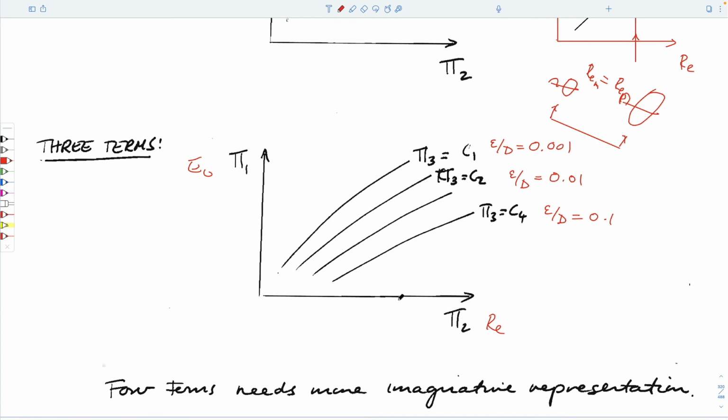But again, if we get, what do we call it, kinematic similitude, that the Reynolds numbers are the same. Reynolds number model equals Reynolds number prototype. That's this curve here. If we know what the physical constraints of our system are, then that defines this point here.